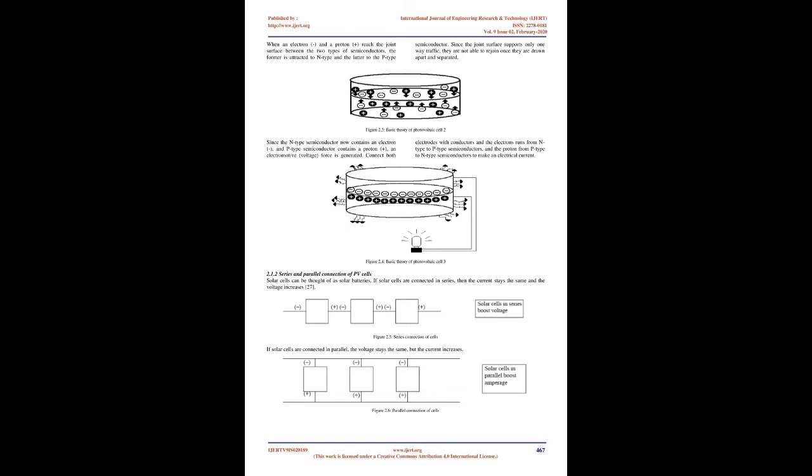If comparisons are made for different time periods or locations, it should be recognized that year-to-year variations in the solar resource will influence YF. The PR factors out solar resource variations by dividing YF by the solar radiation resource, year. This provides a dimensionless quantity that indicates the overall effect of losses and may be used to identify when operational problems occur or to evaluate long-term changes in performance.